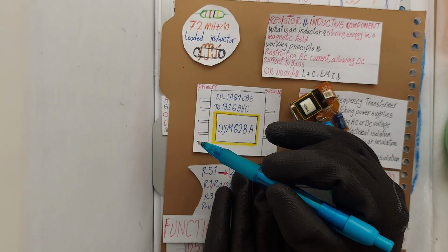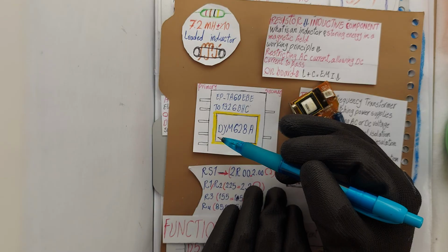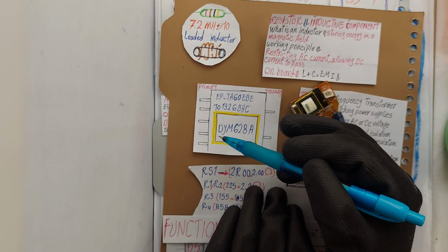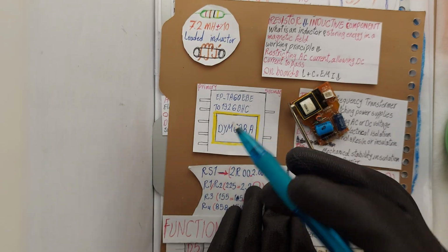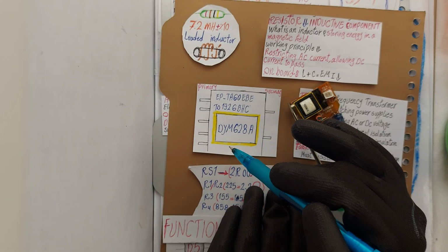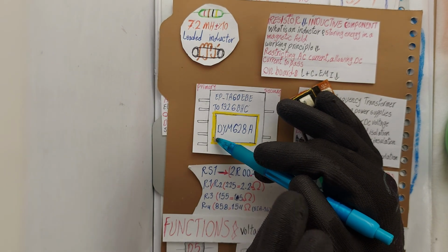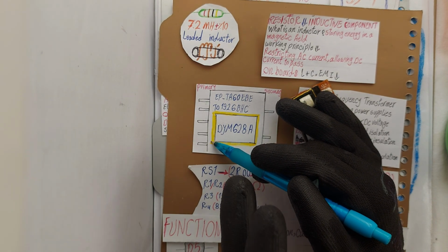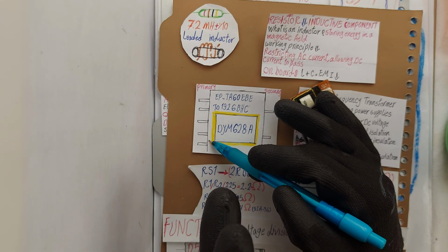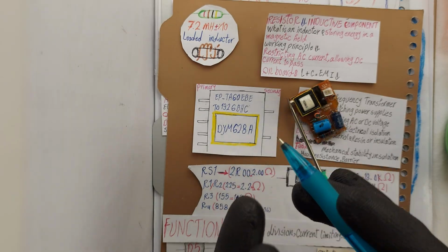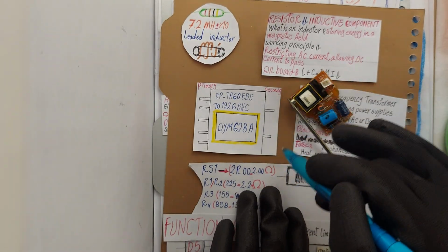And auxiliary pins. These pins serve two purposes: supplying VDD voltage to the IC via a diode or internal path and providing feedback for output voltage for voltage control. Typically, one auxiliary pin connects to feedback resistor, for example right here, circuit, and goes to the IC's FB feedback pin. There may be a diode between the auxiliary pin and VDD as the transformer's release energy powers the IC self-supply. Now we came to the secondary pins.